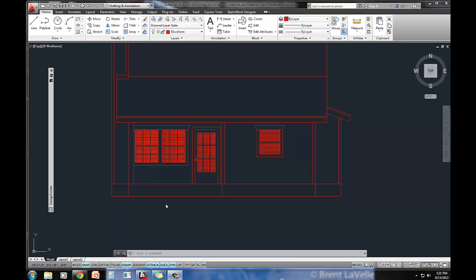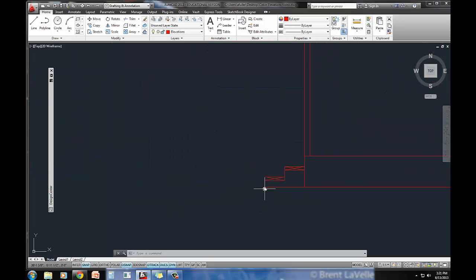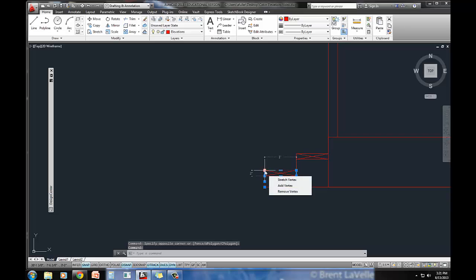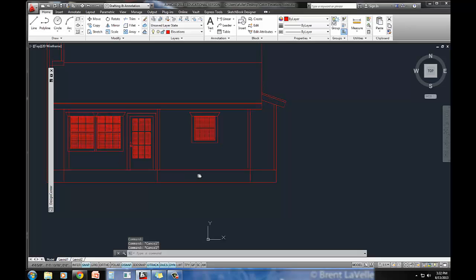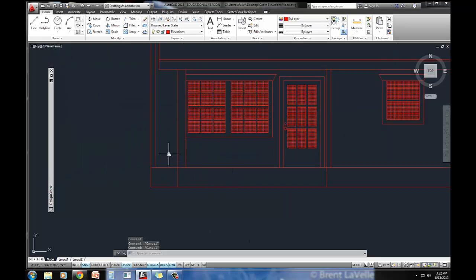In this video I'm going to show you how you can draw the front steps in the front elevation, and we're doing the final cabin project in chapter 12 in your technical drafting book. So we've already got them drawn over here to the side, and if you recall, this is a 6-inch rise, so we've actually got 4 inches here, and then we've got 2 inches from that 2x12, so it's a total of 6 inches.